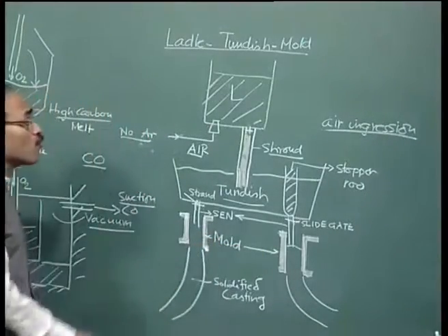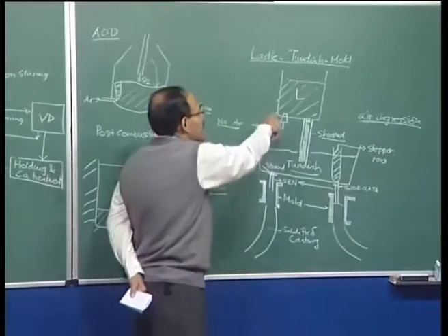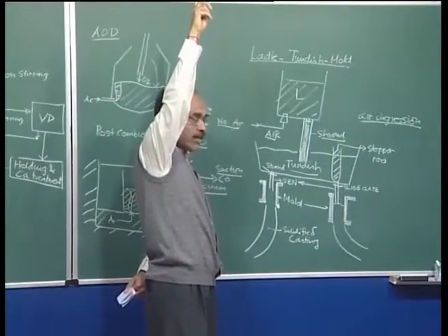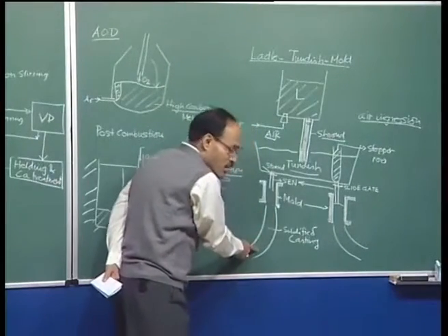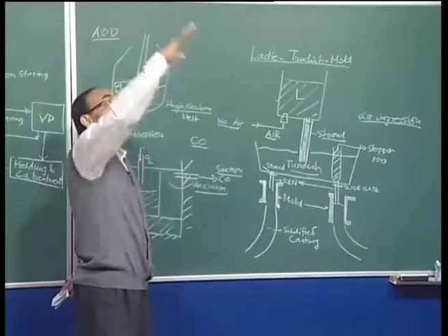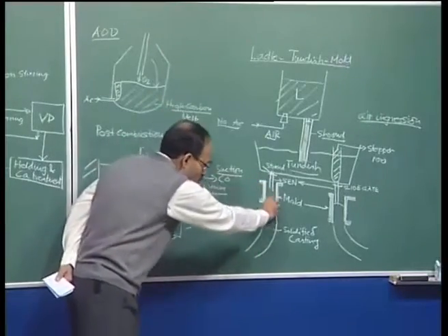This is the arrangement, and we are talking of a height of 3 floors. The ladle is sitting something around 15 to 20 meters above the ground level. These billets, or the slab, are going to be discharged at the floor level. So, above the continuous casting machine, and this is a curved mold. So, you require an enormous amount of space.